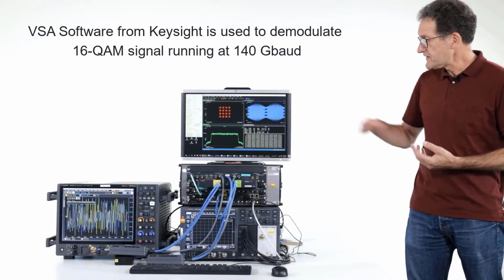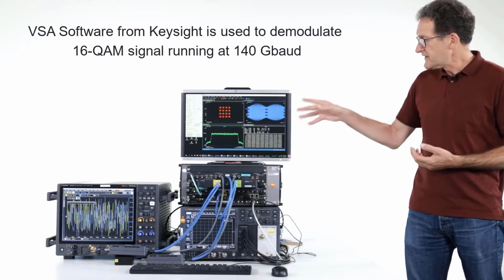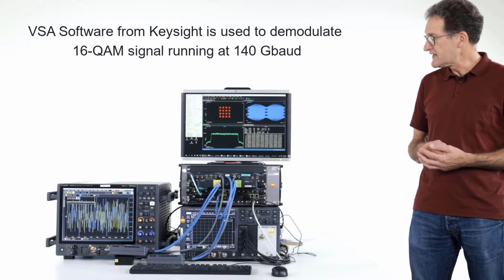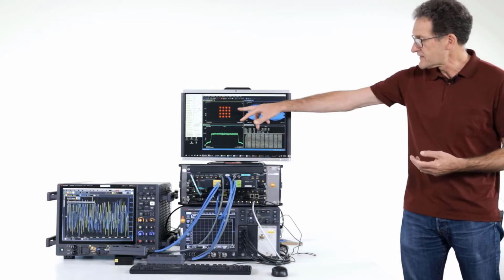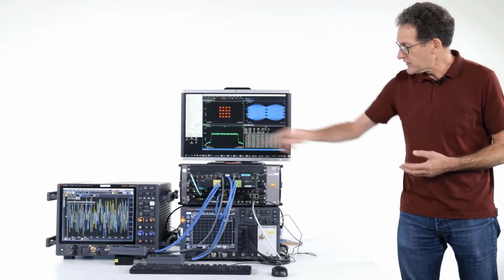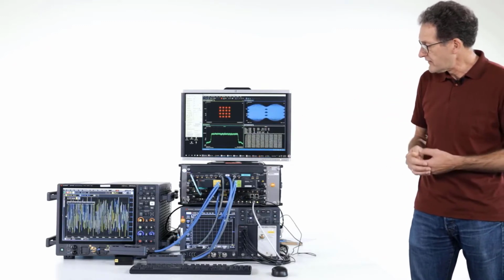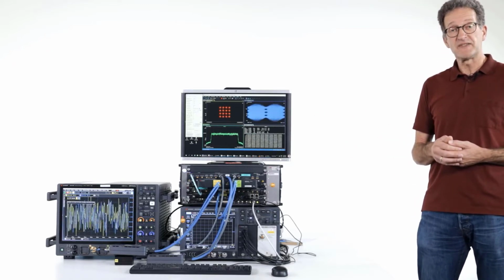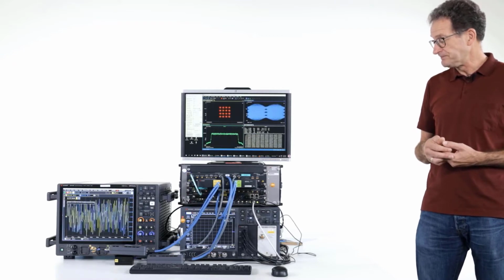On the analysis, we're using the VSA software from Keysight, which in this case is configured to demodulate a 16 QAM signal running at 140 GBaud. You can see the constellation on the top left, and then an eye diagram, and also the spectrum on the bottom left. In this particular configuration, it looks like we're achieving an EVM of about 7% for the electrical back-to-back connection.